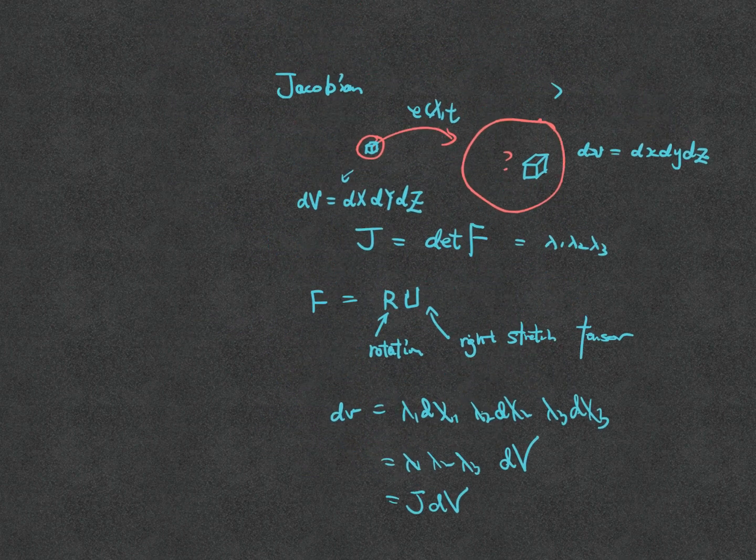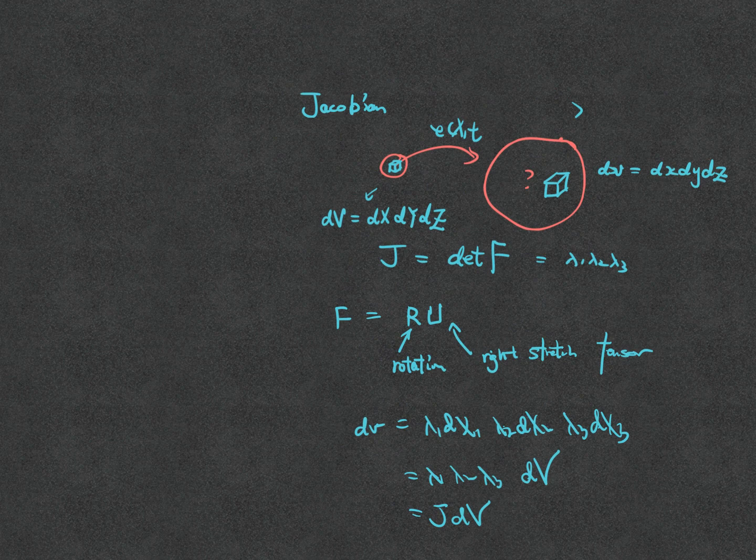Now I do want to emphasize some differences in large deformations, and they are very important. In what we talked about, how do we measure the volume change? We use the trace of epsilon, right? Now here in the large deformation, I use the Jacobian. Okay. Now the trace of epsilon and the Jacobian are not identical. Okay, you understand what I'm saying? So which one is a good way to measure the volume change? Which way is more accurate?